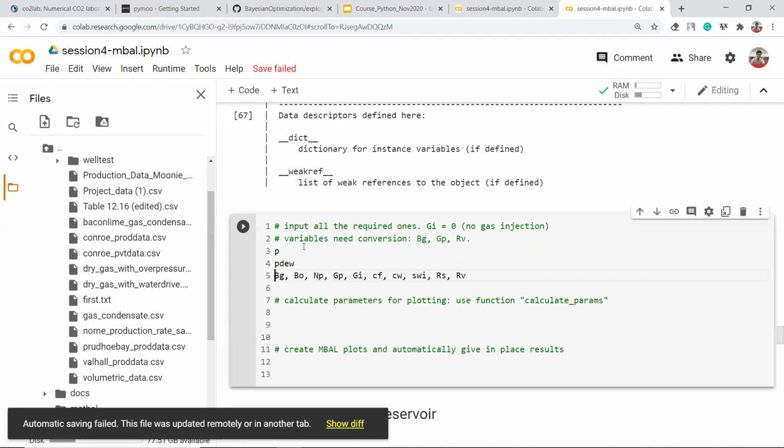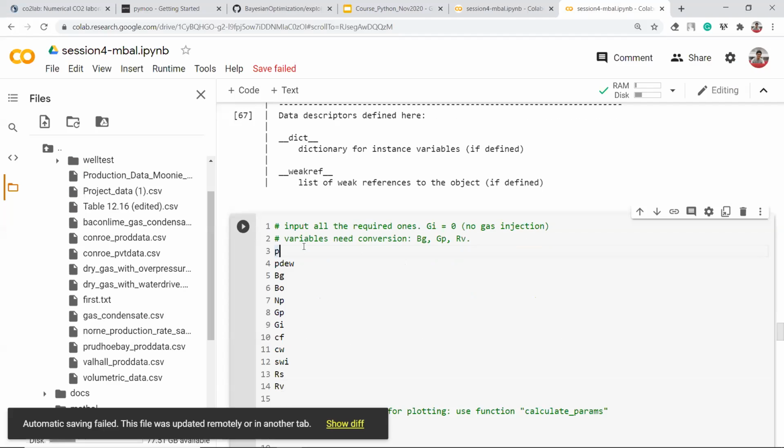If you study it, it is really interesting to see that the reservoir fluid is really unique. First of all, you have the oil, and inside the oil you also have the dissolved gas. So you won't see just oil. You also see other phases, like you will find the gas inside the oil. And inside the gas you also have the liquid. So there are three phases actually: the oil, the gas with dissolved gas, and this dissolved liquid inside the gas.